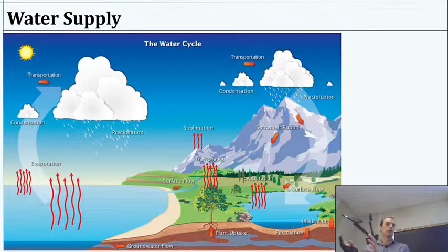As we'll see with some of the septic tank systems, usually there are some guidelines. Okay, you should place your nearest drinking water well at least this far away from your septic system, right? At least this depth, at least this distance, some combination there, right? So some radius. That's the typical procedure. Assigning a number is actually kind of silly in the sense that it would vary, but there's a good practice type of number that we could use, right? That's generally safe or would be safe under most conditions. So that's something to think about for groundwater.